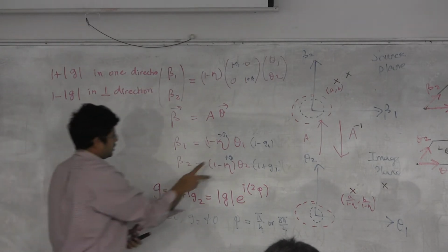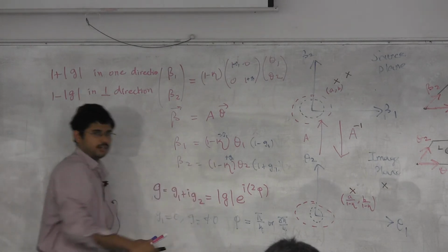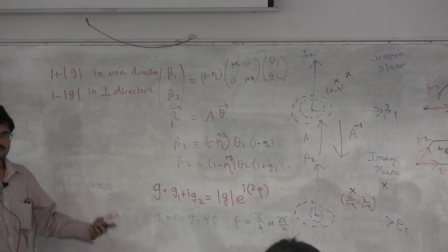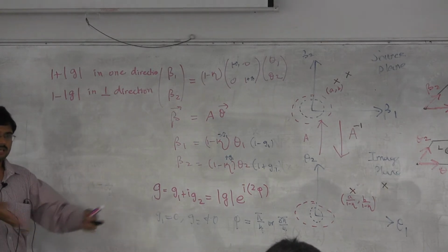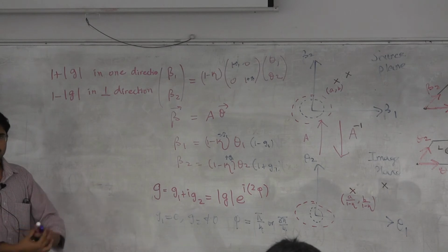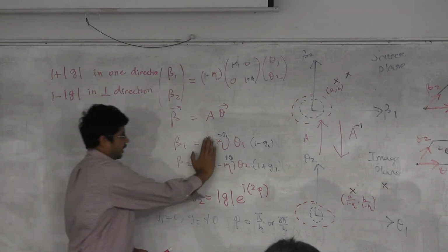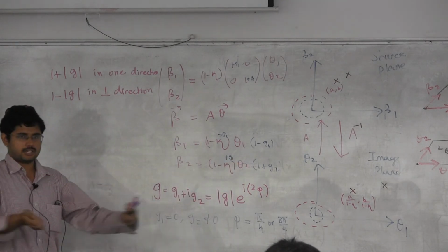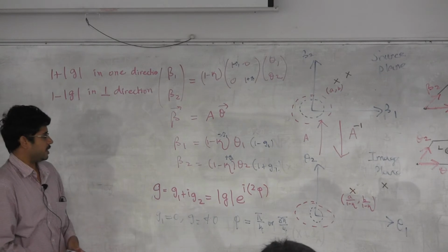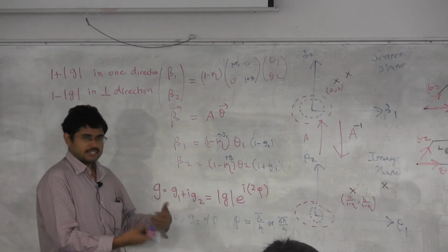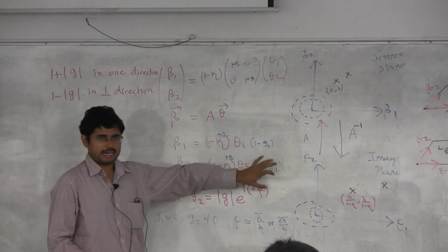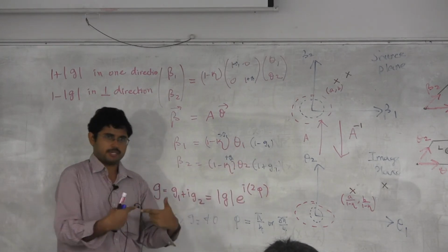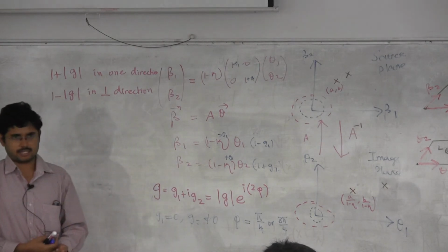If in addition kappa is significant, then there would be an overall stretching or contraction. So it could get stretched in both directions, or contracted in both directions. But ignoring this term, the shear itself will always stretch in one direction and contract in the other. So we have separated this distortion into an isotropic part and an anisotropic part. The anisotropic part is always extension and compression. It always occurs in pairs.